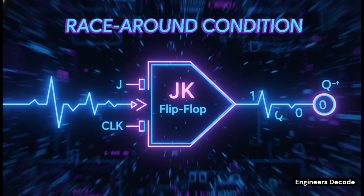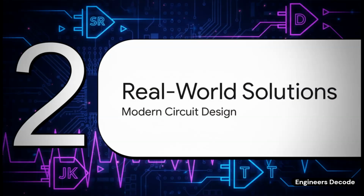But guess what? It introduced its own problem, the race-around condition. See, if J, K, and the clock are all high at the same time, the output just starts flipping back and forth, over and over uncontrollably. By the time the clock goes low, who knows what state it'll land on? It's a total gamble. And this is where the real-world solutions come in.